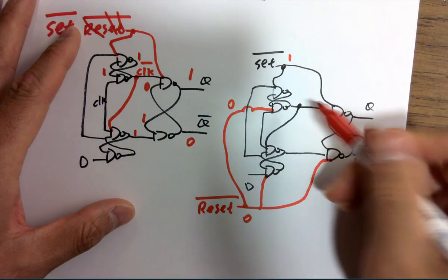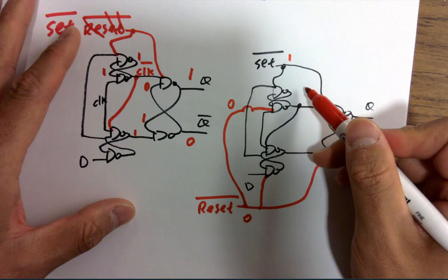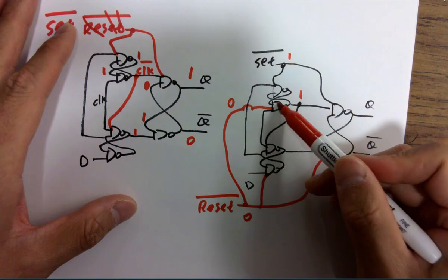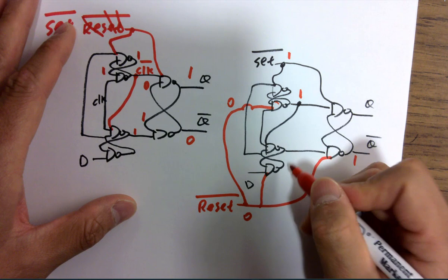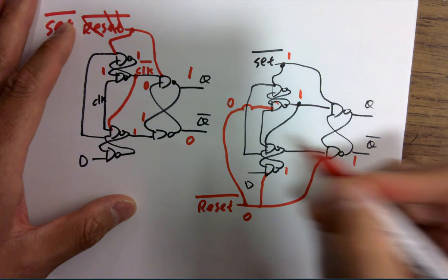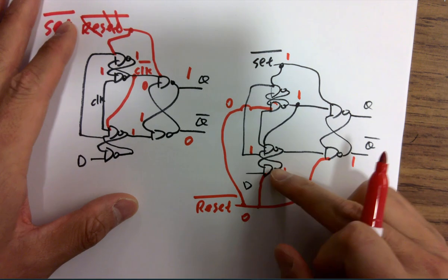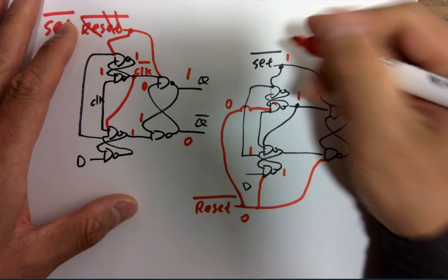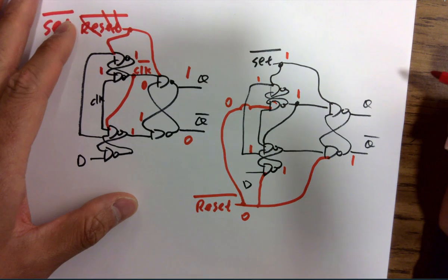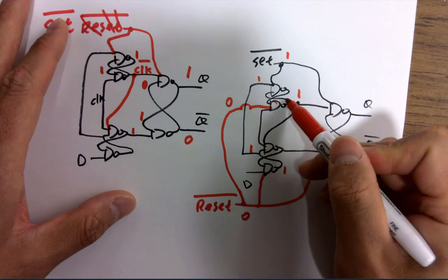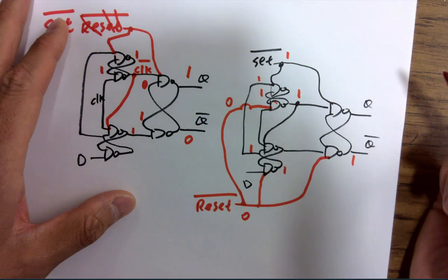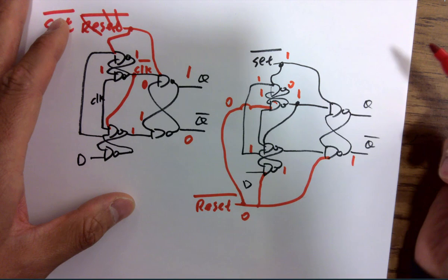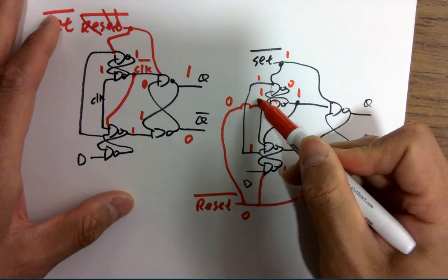So 0 here, this is getting killed, got a 1 for sure. Right, this guy. And same for this guy, 1, 1, right? So got a 1 here, being fed back. This is 1, this is 1. So we know this is a 1, so this is being fed back to this guy, it's 1. 1 1 1 NAND, you got a 0 here. 0 here.